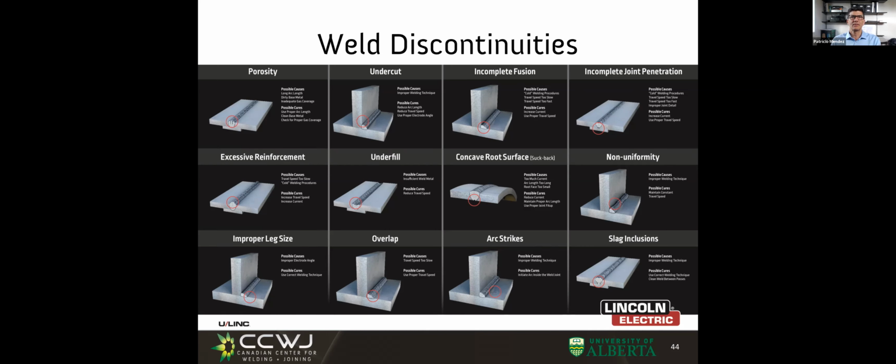The reason is, in welding, what matters is fitness for service. So if I have a porosity and my code standards or client specifications deem that a certain level of porosity is not a problem for service, then that porosity, which we can call a discontinuity or an imperfection, is not a defect because I don't need to fix it.